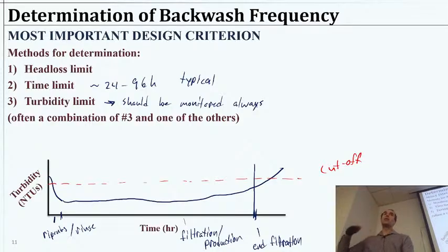Turbidity is starting to increase. We know we have to wash this filter. So then we would perhaps do an air purge. That's a little bit optional. And then backwashing.